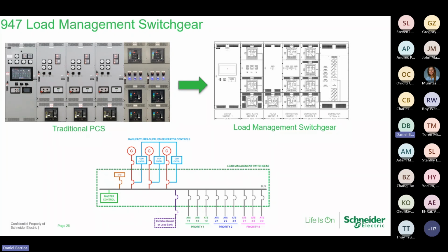We've taken those three sections, section 2, 3, and 4, and we have combined those into section 2 where we have the breakers for each of those and some type of metering, but you do not have all of the controls in there. And then obviously the load bank section and going into your distribution, including some type of an I-line panel or such. We want to discuss this with you.